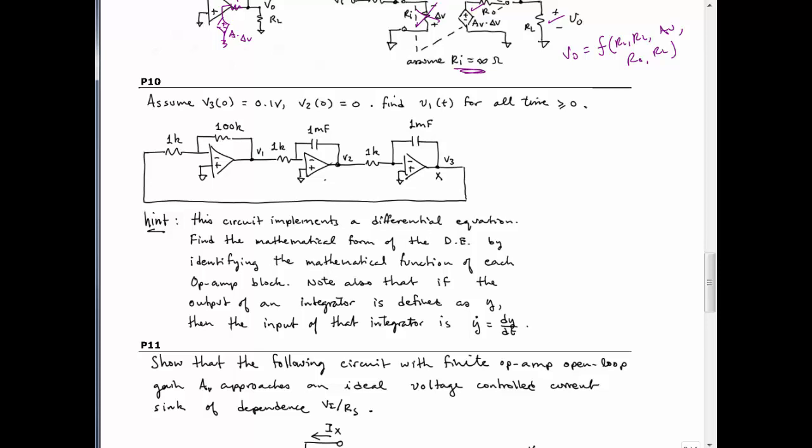So I mentioned at the end of class today that analog computers were the first computers to solve things like differential equations, nonlinear differential equations, and they were solved by actually building a circuit of op-amps. And the basic functions that we needed for an analog computer, or to describe a differential equation, was summing and difference, I'll call it a block, a function, a gain block, okay, and then an integrating block.